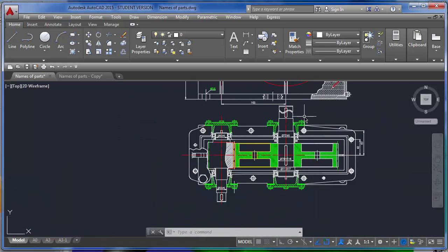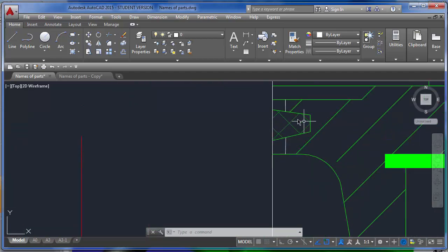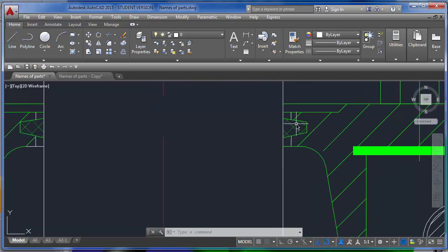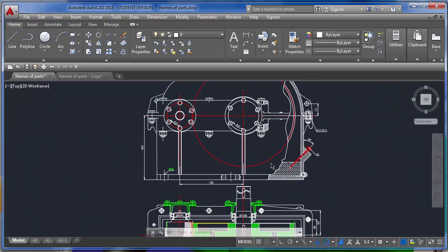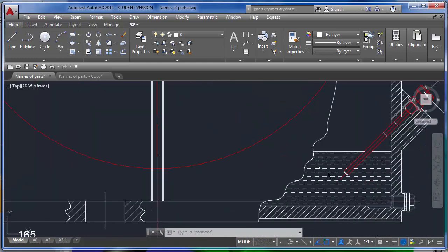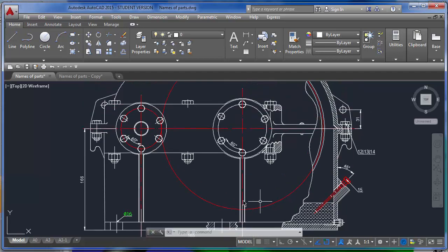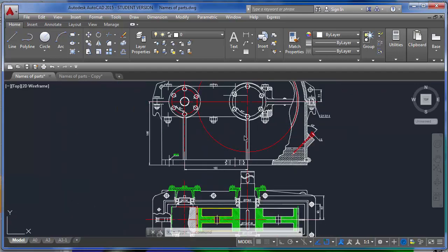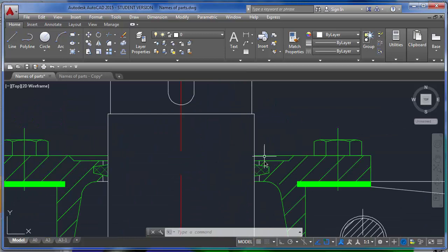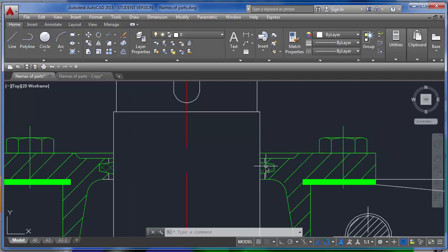Okay, and one more important part is this little guy here. This is a rubber ring. So actually this whole system is under this engine oil. These are oil. So this guy rotates, and engine oil goes here and goes all the way to the other parts. So if we have any clearance here, the engine oil will go out and it will create leakage. So to prevent leakage of oil, we put this guy here.